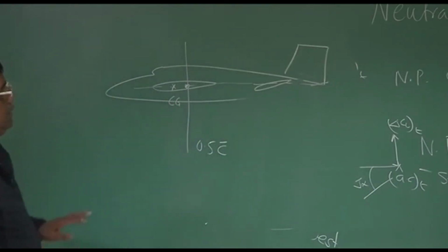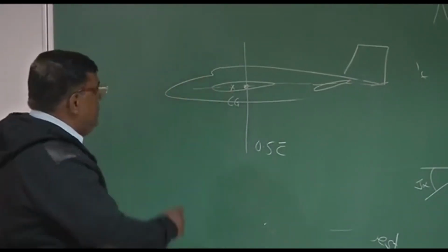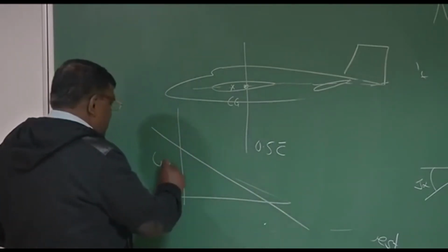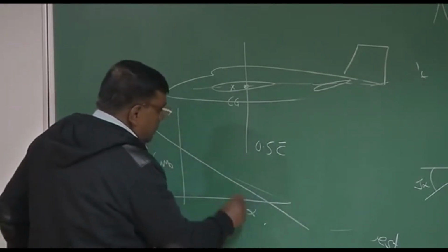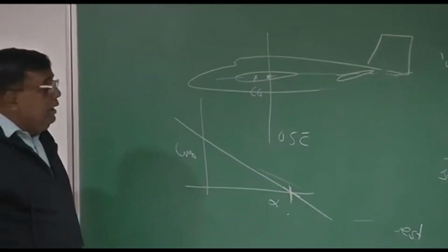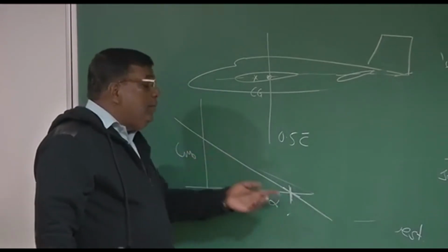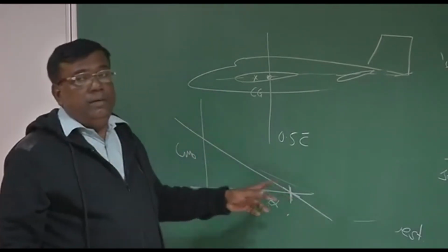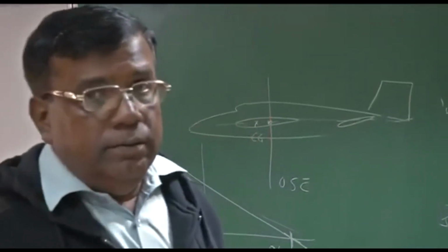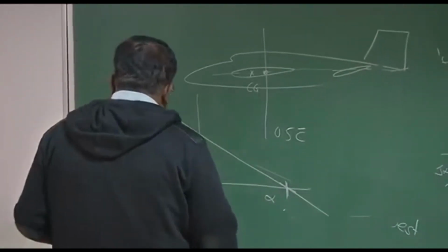And the meaning is, if I fly this airplane, I'll be able to generate Cm naught positive, and the slope at trim dCm by d alpha will be negative. That tells me clearly I can trim this statically stable airplane at a positive angle of attack alpha. Okay, because I could make Cm naught positive. Okay, so this was the problem.